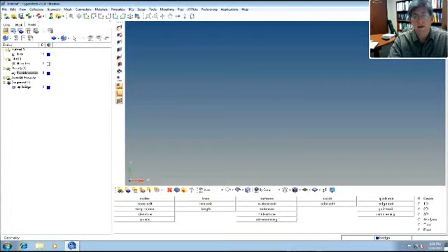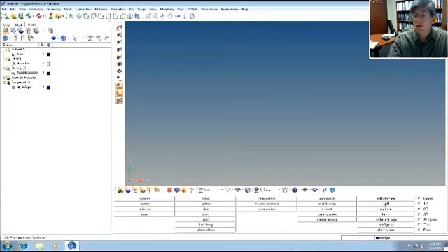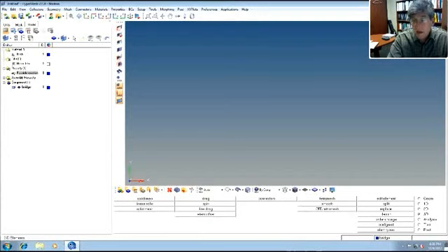Geometry allows you to create things like points, lines, curves, surfaces, even solids. You use this 1D menu to define one-dimensional elements like bars and rods and rigid elements. You use this 2D subpanel to mesh things with two-dimensional elements like linear strain triangles or constant strain triangles or four-node quads. Again, for three-dimensional mesh generation, you have this panel.